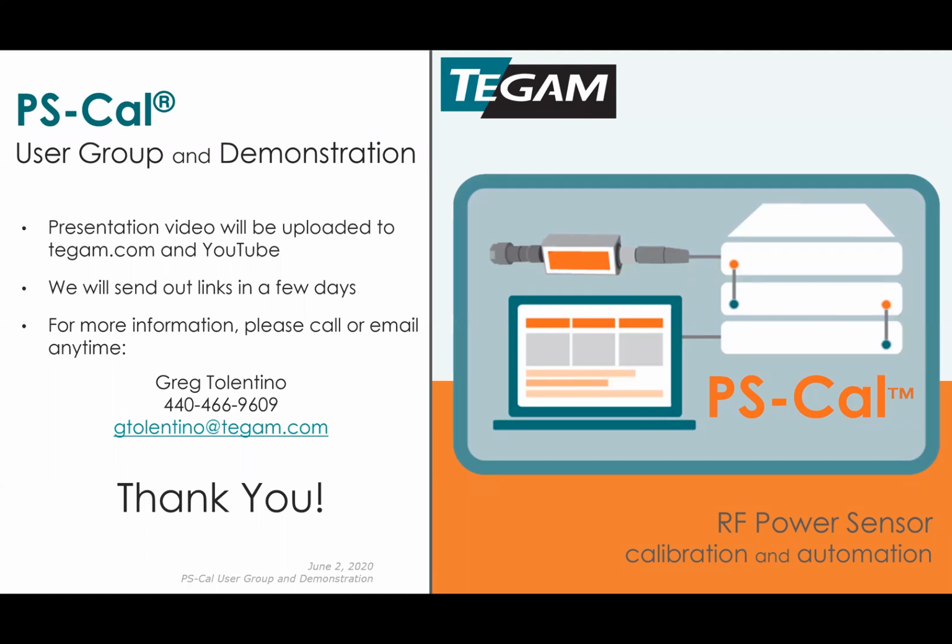You're comparing everything to the 50 megahertz reference, and that's the key piece there. So calibrating it to the 50 megahertz reference out of the meter isn't entirely important. What's really important is how all the cal factors compare to the 50 megahertz that you measured in the actual calibration.